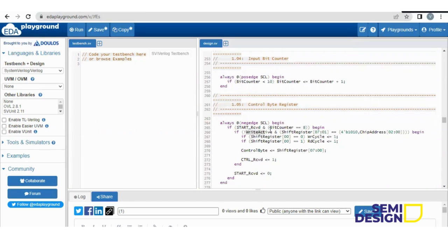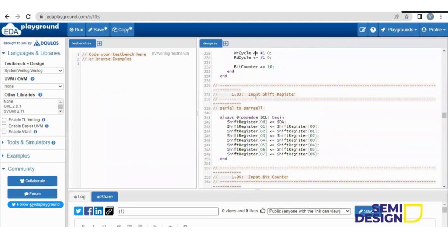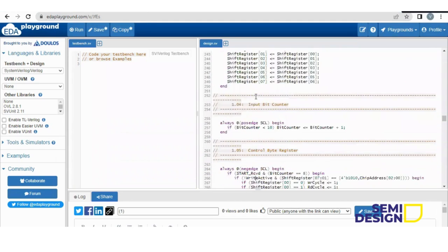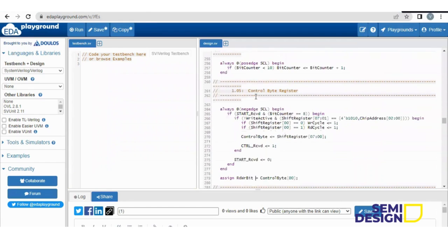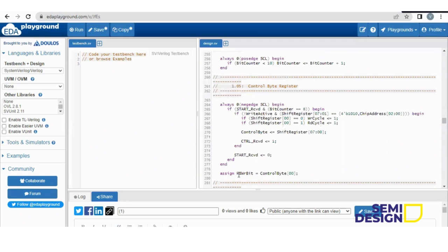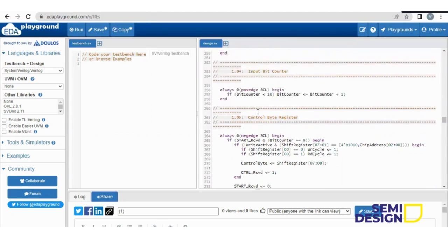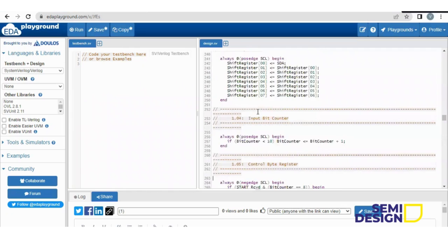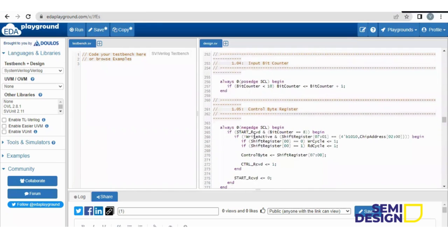Then write active is equal to 0. This write active, basically, I think it is the write-read signal. Why is this signal used? Okay, I will tell this later, but first let me explain what is happening. Sorry, write active 0 means the write operation has already completed. That means into the shift register, the write operation is completed. No more data is being taken by the shift register.